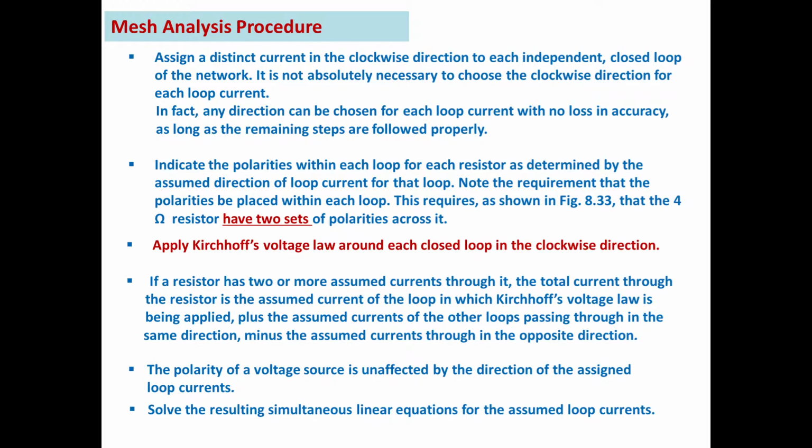Now this is the first step. We have to identify the mesh and then choose the clockwise direction. We are assuming clockwise direction, but it is not necessary to assume clockwise direction. In this course, we will assume the mesh currents to be in clockwise direction so that it makes our analysis a little easier and uniform for all of us. Then we have to mark the polarities. Then we have to write Kirchhoff's voltage law, and then write the equations and solve them.